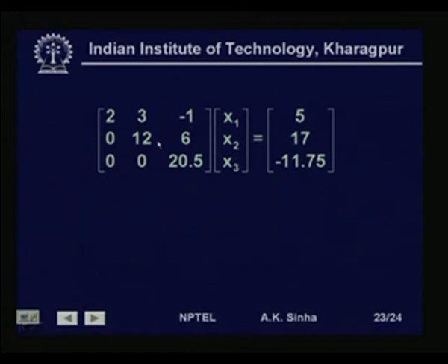So, Gauss elimination is of course the simplest of these methods and is quite effective and is very much used for solving linear sets of equations which come out from the Newton-Raphson load flow equations. So, this is what we will do today, and in the next class we will talk about how to solve the Newton-Raphson power flow equation using this direct solution method.